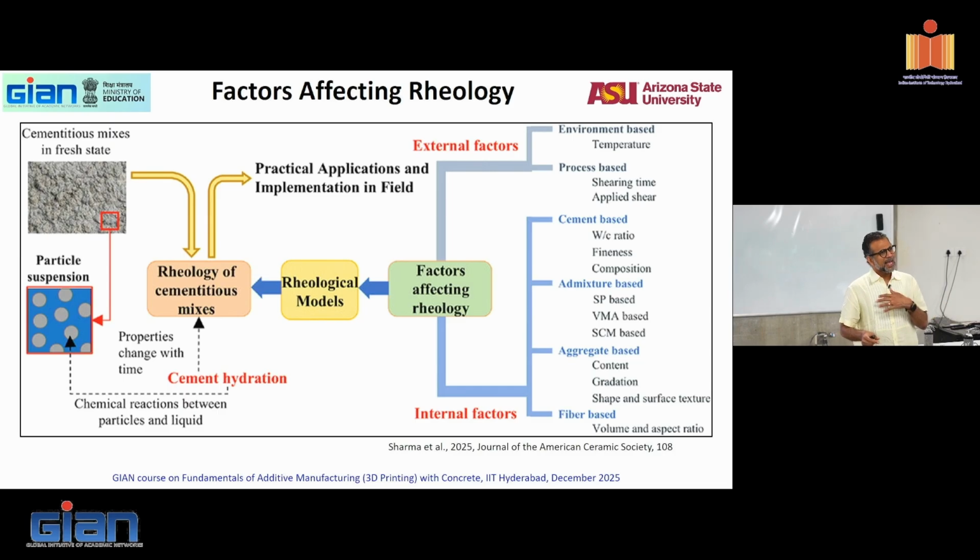Rheology, what does it depend on? Everything that you can think of. Cement content, water cement ratio, type of cement, where did I buy the cement from, who mixed it, how fast did I mix it, what was I doing when I was mixing it. All of those factors will influence the rheology. Aggregate content, gradation, fibers. So none of those are unique, pretty much everything.